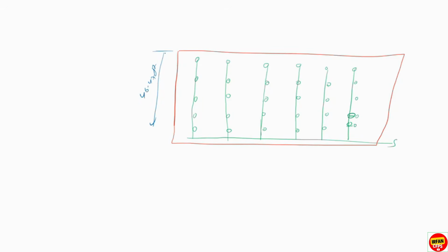46.47 feet, right? This length from here. So for example, we get till here. Now here we have 1, 2, 3, 4 sprinklers in this design area length, right? 4 sprinklers we are getting for now. But whether you need to consider the 5th sprinkler or not depends upon the 4th sprinkler. How? I will explain. So now here, this is the 4th sprinkler, assume. This is the 5th sprinkler.